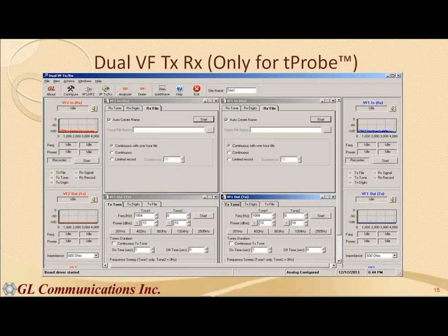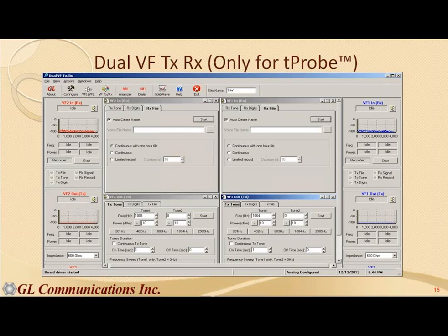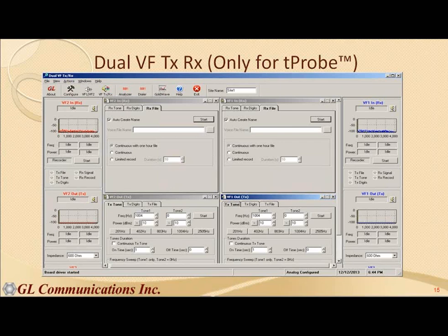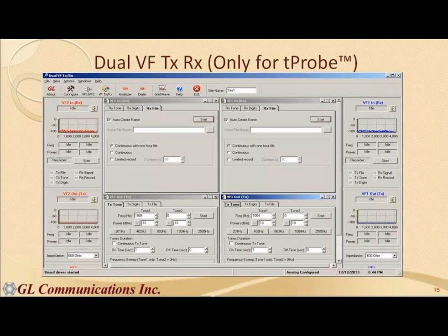So you can take our probes and convey that SNMP type of information, which is very basic information, via SNMP. We have people here who are SNMP experts who can show you how to do that. You can use our probes to extract basic information about framing or connection, in sync, out of sync, loss of carrier, loss of sync, yellow alarm and remote alarms, and convey that information via SNMP to a network monitoring system.